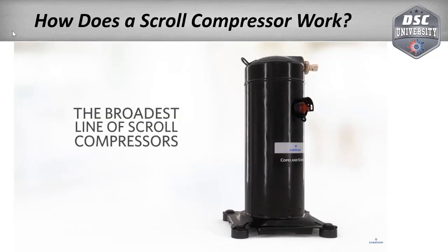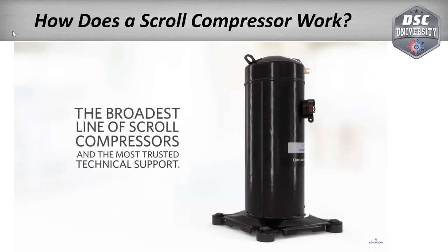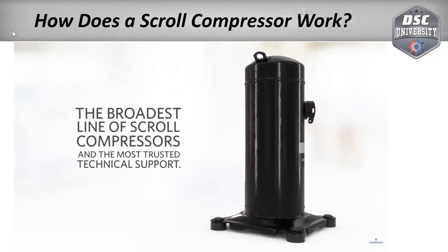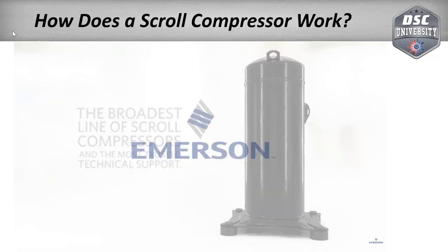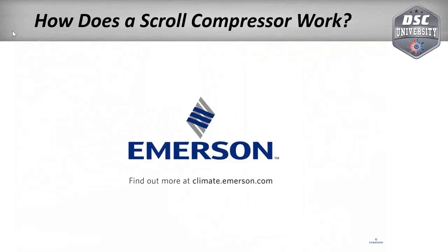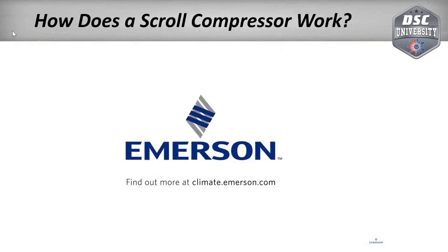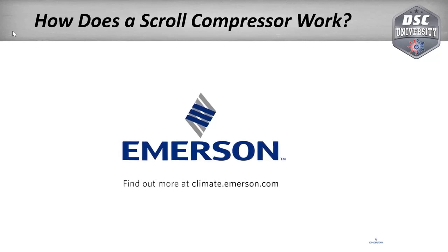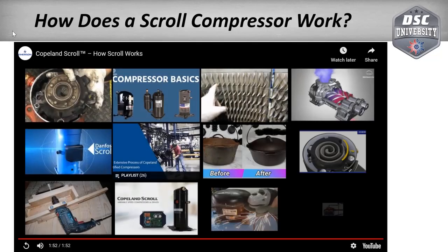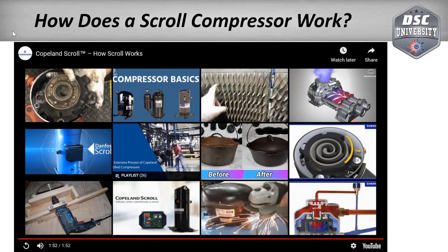Whereas if you go back to your old compressors, which were called reciprocating compressors, they were built like a car engine. You had a horizontal shaft, and it was just like a crankshaft, and you had two pistons going back and forth like this, and they had valves that actually would open and close. So there were a whole lot more moving parts and a whole lot more things that could fail on those.